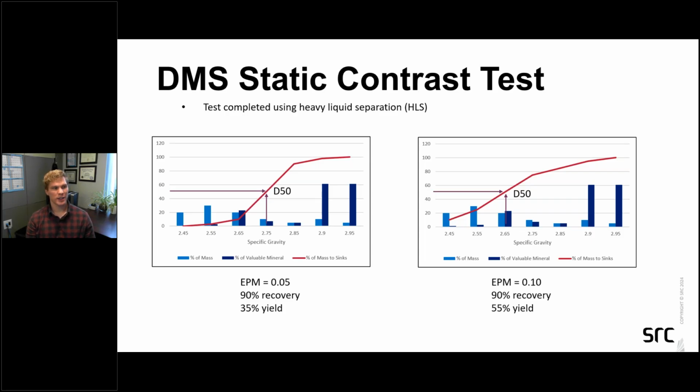And you could really also think of this like, if you had, say, the one on the left, if we were doing an ideal separation, you got 0.05, that's great. But maybe when you actually did it realistically, you got 0.08, something like that. So it's a little bit of a lazier curve. So now you're getting more displacement, worse performance. You might have to adjust your set point to really meet the minimum thresholds for grade or recovery. And that's that. Ideal gives you how good it can be, and then the capacity test tells you how good it is actually going to be.